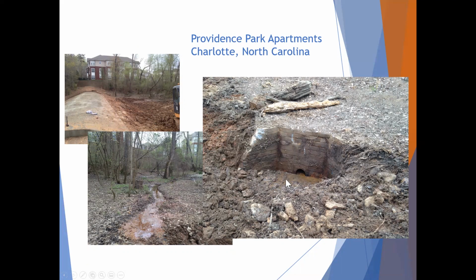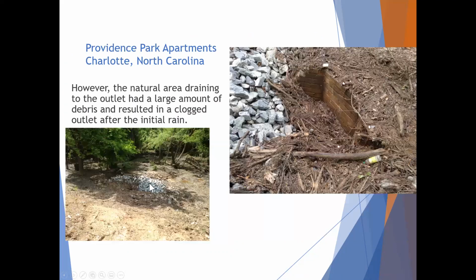We finally found this head wall. The sediment was basically up all the way to the top of it, so it was hidden. We just saw a little trickle being sucked down in the ground and figured it had to be some sort of outlet there. So we cleaned this out, got it functioning again, and put a riprap ring around it to try to protect it.